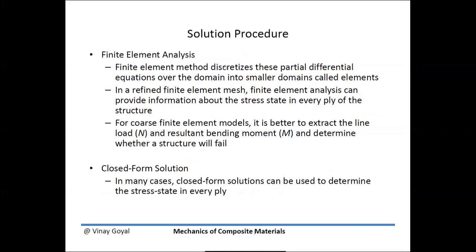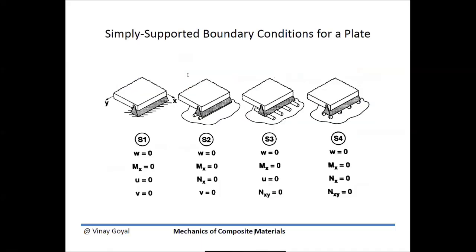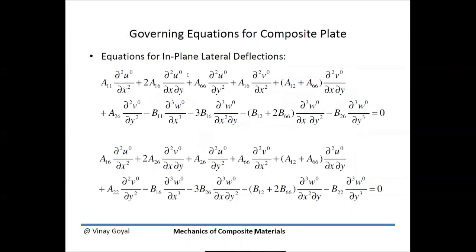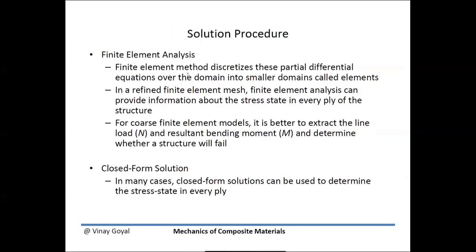So what is the solution procedure when you go to finite elements? I'm not going to go into the theory of finite element analysis. If you're interested, go ahead and subscribe to my channel, and I have a whole set of finite element notes. But for this particular lecture, what is finite element analysis doing? We're discretizing the partial differential equations over the domain using smaller domain elements. As you can see here, solving these three equations looks highly complex. But if I can try to solve it for smaller domain elements, I could get somewhere.